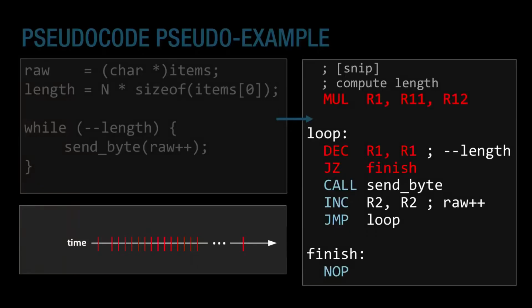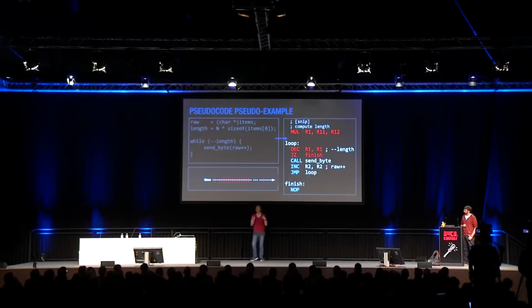In order to do this, we don't necessarily know at what points exactly the device is going to be vulnerable. We can guess that it's in those instructions in red that we're likely to have the effects we want, but we don't know when during those clock cycles we might want to glitch. We don't know what kind of glitches are going to be effective, or if any are going to be effective on a given system. So we need to be able to experiment, and for those experimental results to mean anything, we really need a very precise way of identifying time relative to the thing that is executing the program itself.